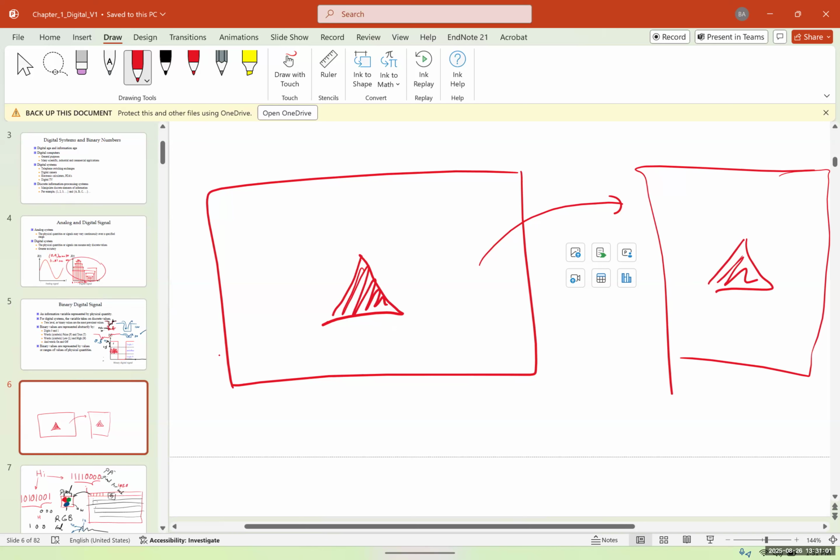If I have a digital signal, I can just send this object in the middle, and tell the receiver that everything else in the background is white. So I have a red triangle in the middle, everything else is white. Because my background is stationary, I can send that picture once and send the moving object every 5 seconds, or 3 seconds of refreshing. So now instead of sending the whole picture, I send like 1/20th of the picture.